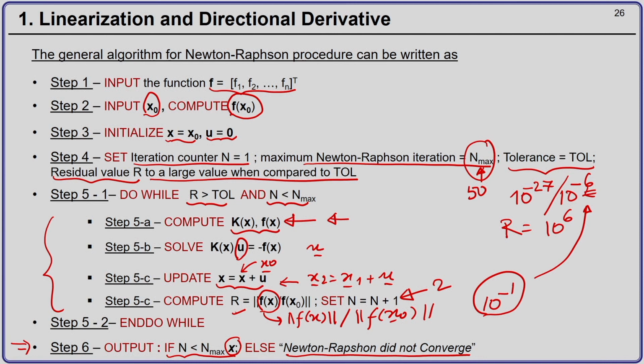It might mean that there are some other convergence issues, which you can go back and handle using arc length method, line search. All these kinds of methods can be applied. But here for our second problem, for a given system of nonlinear algebraic equations, the following algorithm should work.